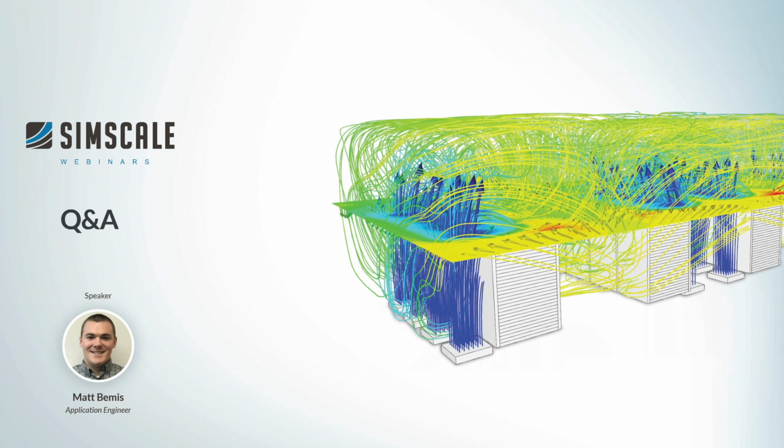Let's see. I've got a couple questions here. Number one, does SimScale support fan curves for the CRAC units? That's a great question, and the answer is yes, which is pretty exciting. That's actually pretty new. As a boundary condition, instead of just saying, okay, the flow rate is 3.92 cubic meters per second, we all know with these CRAC units, sometimes the underfloor plenums can get too busy, have too much stuff, and the supplied flow rate is less than maybe what's spec'd.